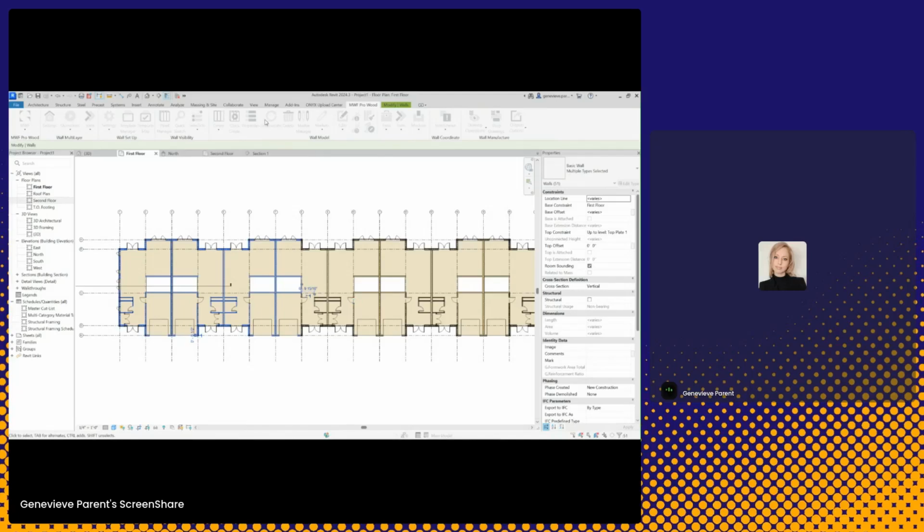Sometimes you might realize in a project that you have certain openings that are specific to this specific client, and you get another client down the road, and then you kind of want to steal those openings. You can go into your project and simply export those markers. You can even bring them back into your company template file to use for future use like that. You don't have to redo all the work.